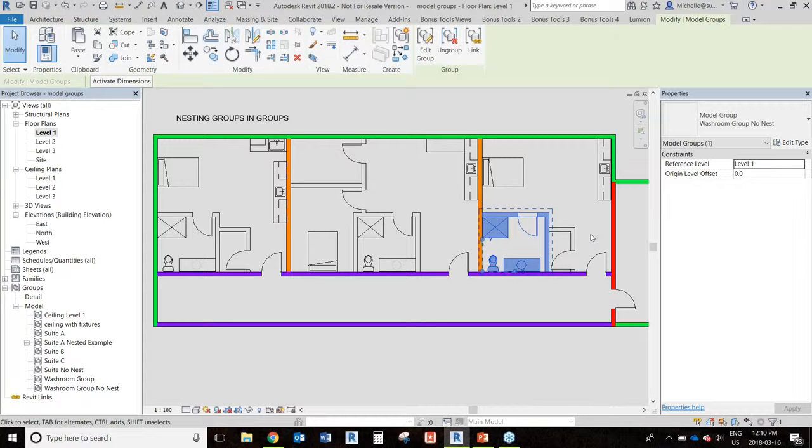Not to say that this is an absolute. Maybe in the beginning when you're doing design, you might nest some of this stuff in just to get stuff multiplied and placed, but this isn't something that you want to continue throughout the duration of your project. In design it might be fine because there aren't a lot of elements and complications going on in your model, but as the model progresses, gets more elements in it, gets potentially more warnings, more slowdown, we want to make this as lean of a process as you possibly can, just so that you avoid problems down the road, especially when those problems seem to happen right around deadlines and time when you really don't have time to deal with it or fix it.